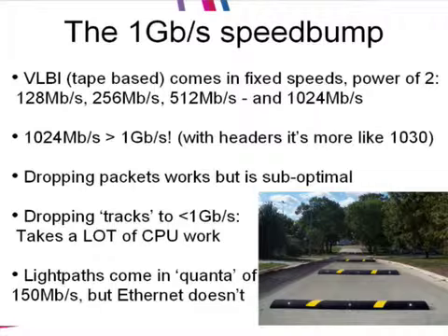One of the things we've tried is to randomly drop packets to bring it down to, say, 980 megabit. But it's fairly difficult to then still get a calibrated image, because you're not sure which packet you dropped. And the other problem is we are all the time calculating basically the correlation between 2 telescopes. Now if one telescope is dropping 5% and the other is dropping 5%, and these drops are not synchronized, then you're actually losing twice that. So you pay a big penalty in sensitivity when you do it that way.